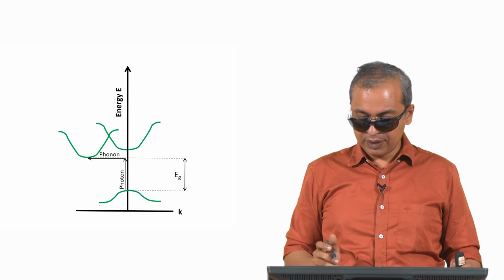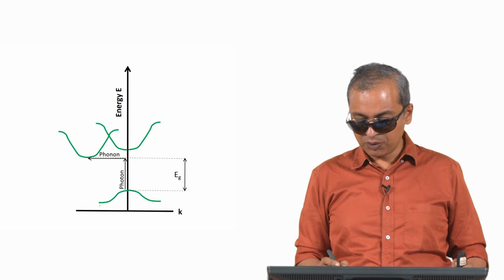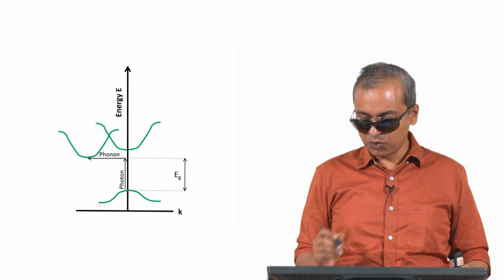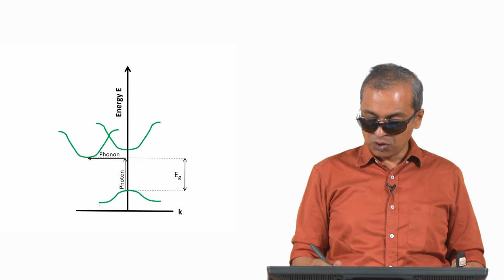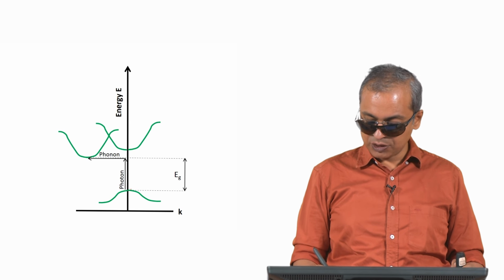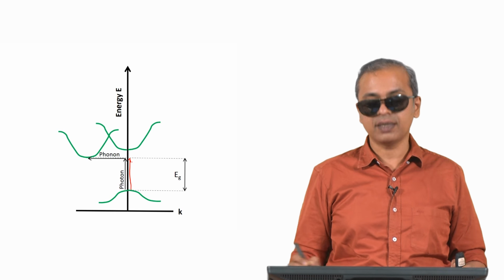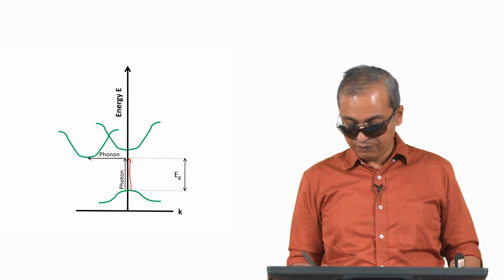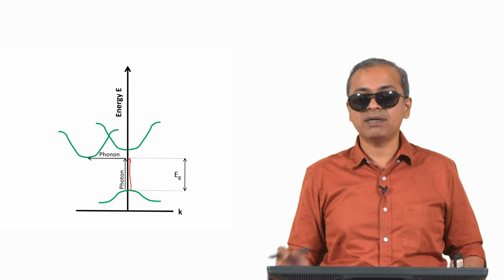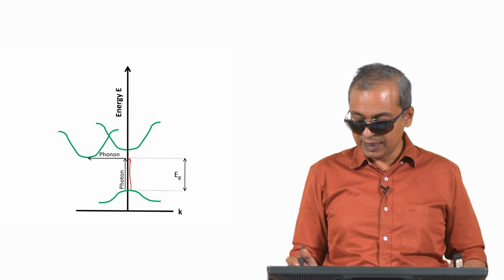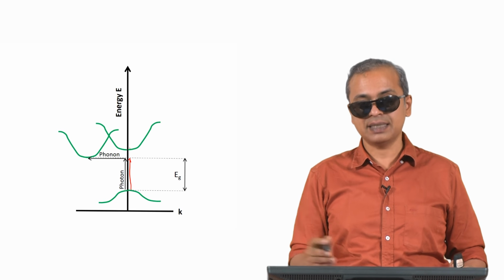So, what happens within the material is that you now end up requiring a two step process. I am just taking the indirect band gap semiconductor here and highlighting that. Normally we would simply require E equals h nu to get your electron up into the conduction band, but we find that when you do E equals h nu and you bring the electron up, there is no available site where it can go and sit. It is still sitting in a forbidden gap with respect to that direction in this example that you see.